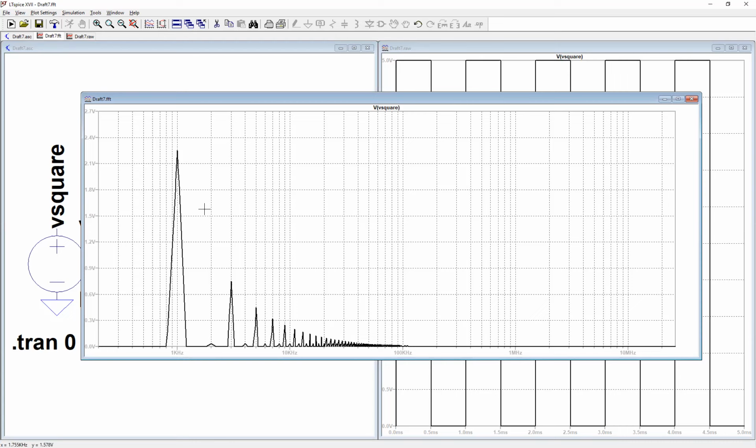It's much more similar to what I showed you in the MATLAB script in the lecture, and it has many peaks, many harmonics, and the harmonics start to decrease, right? However, there is still something that may make you wonder a little and say, but this does not make so much sense, because the square wave is made of infinite harmonics, because my signal is periodic. But again, here I see a triangle. It's not really a line. You remember a harmonic is represented just by a line, but this is not a line. This is a triangle, and I have many triangles here, right? So why is that?